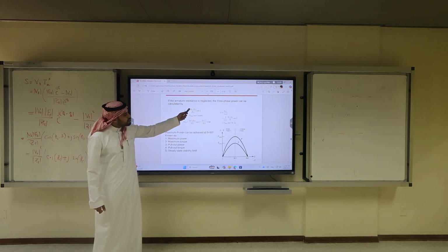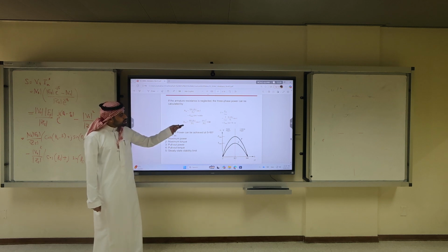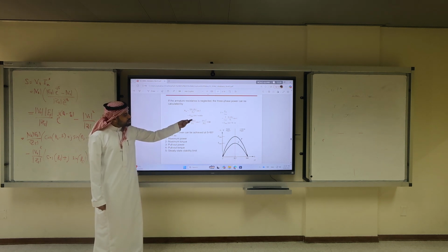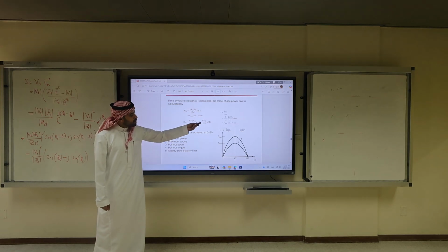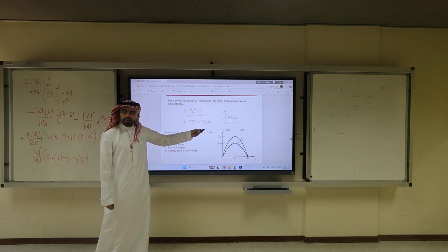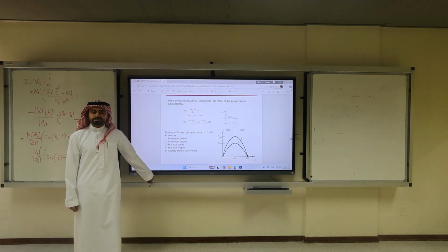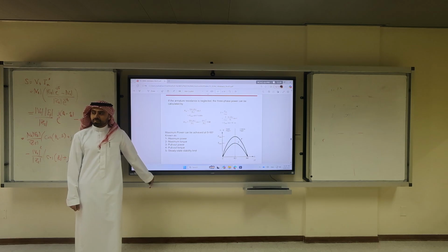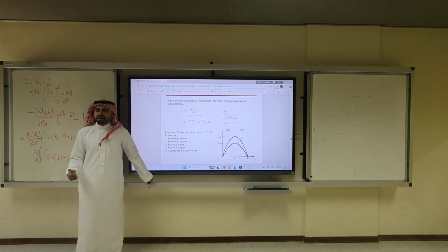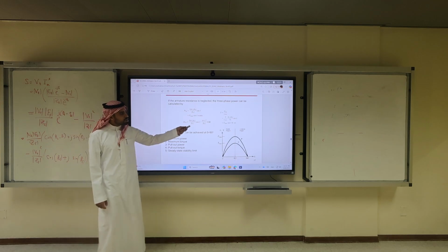The real power is 3 V_T E_F over X_s sine delta, and the Q is 3 V_T E_F over X_s cosine delta minus 3 V_T squared over X_s. Do you remember these two equations from EE 360? Yes, it's very important. Now, all of you have access to EE 360 slides? Yes. So have a look at it and you will remember these two equations.